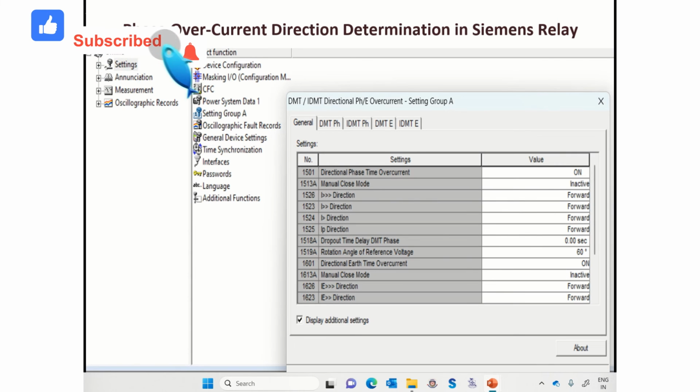for the backup protections, and you are using both as backup protection for main 1, main 2, and if you want to have the same operating region, then you have to select RCA in one as 30 and one as 60, then only it will match, because both are using different terminologies.